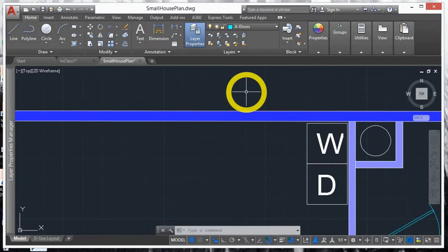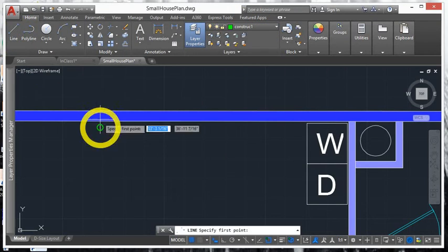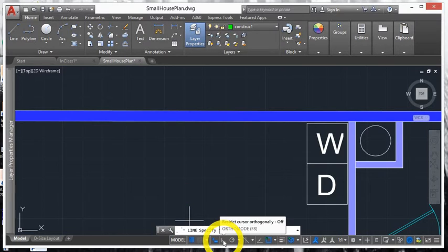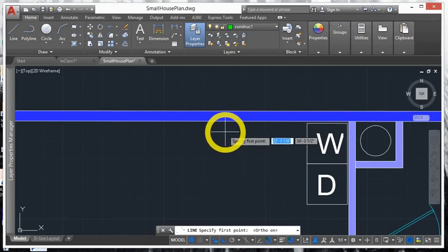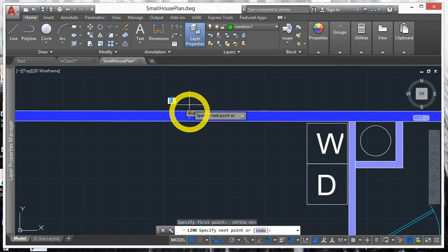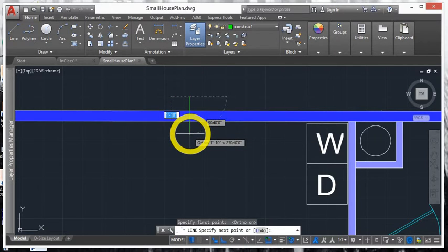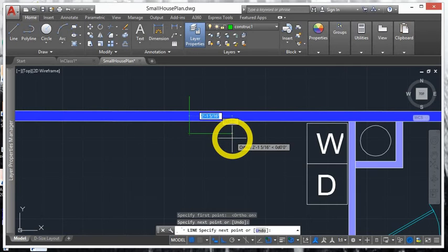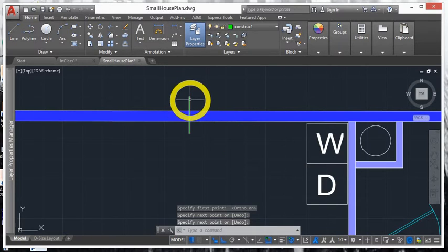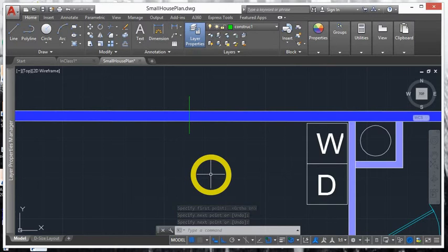So this is fairly straightforward. We're just going to use construction geometry. I'm going to jump over to a construction layer. I'm going to use the line tool, making sure that ortho mode is turned on so that I get nice straight lines. And I'm going to make a single line that's taller than the thickness of the wall. And he's going to be the fence object that I'm going to use when I use the trim tool.